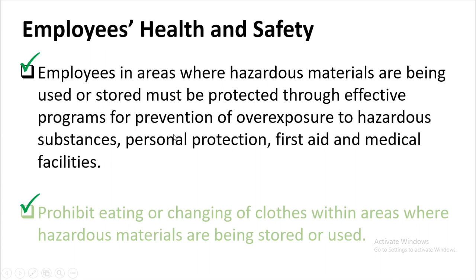And then of course, bring only a small amount of chemicals to the site, only what is required for the job, and chemicals that they can finish in the same shift. Don't bring so many chemicals that they cannot use in one shift. And of course identify the personal protective equipment, so they are protected. For example, there are filters for that specific chemical. So we need to read the method statements or material safety data sheets and consult with the safety department to check what personal protective equipment is applicable for such chemicals.